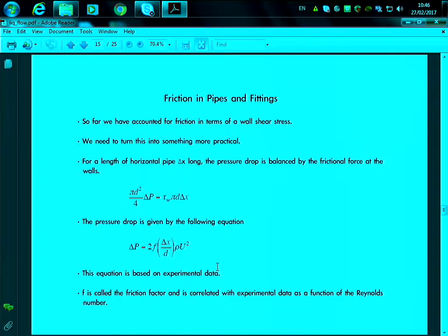And that is reflected here. So why do we multiply by 2? Because we want to compensate for the Fanning friction factor. Here we are using the Fanning friction factor. Why not 4? Because it comes from the derivation.